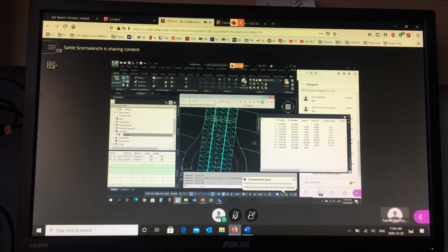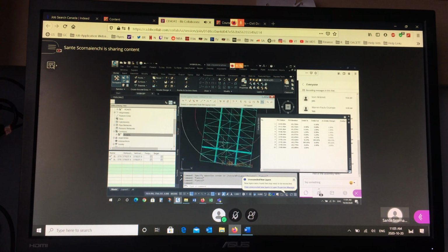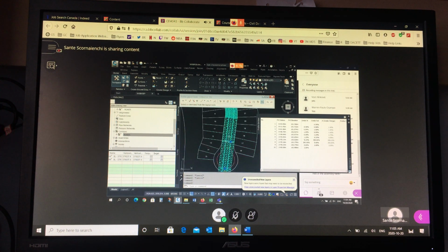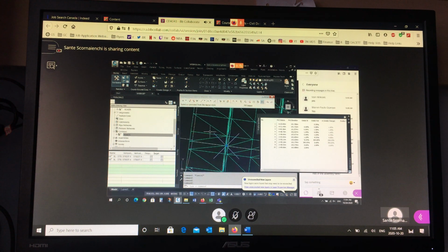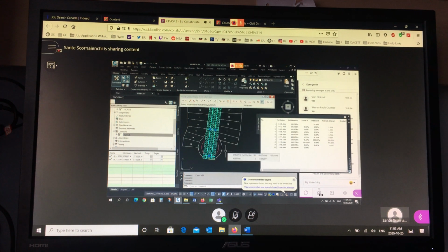So here's what we do with those 3 points. I'm going to grab that point. That's the beginning, there's basically one in the middle of the profile, and here's the end of the profile. These 3 points give me the station for the PVIs in the profile of the gutter of the cul-de-sac, and the surface that we're looking at will also give me the elevation of those 3 key points. Every other point is wrong in terms of their elevation, but those 3 are correct. They are what they are now, and they will be what they are now when I'm done. They're just going to have a different way of getting there around the curves.